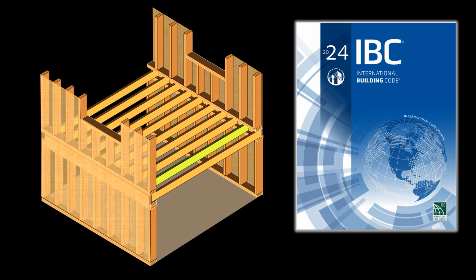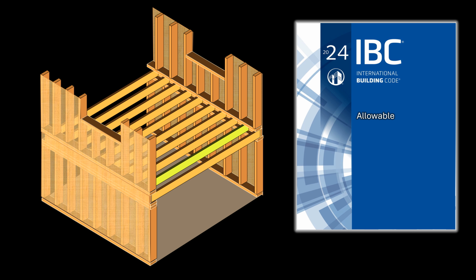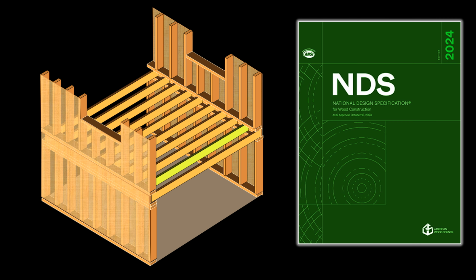The requirements for allowable stress design of wood are provided in Section 2306 of the IBC. The applicable standards for the design and construction of wood elements are provided in Table 2306.1. One of those standards is the National Design Specification for Wood Construction, also known as the NDS, by the American Wood Council. This is the primary standard adopted by most engineers in the United States for the structural design of sawn lumber wood members. We will use the NDS standard in this example.